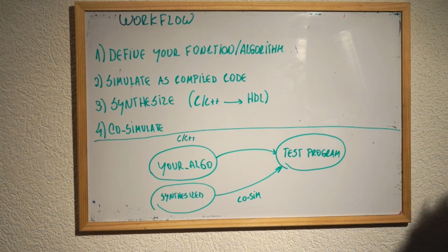This first lab, we're going to show the same algorithm that was the final algorithm that we showed in the last video of the FPGA training. It's the divide algorithm. So we are simply going to write the divide algorithm in C, and we're going to use Vivado HLS to generate an IP core from this code in C.